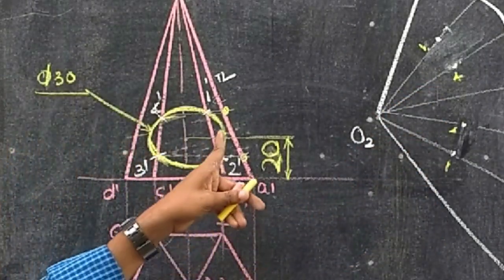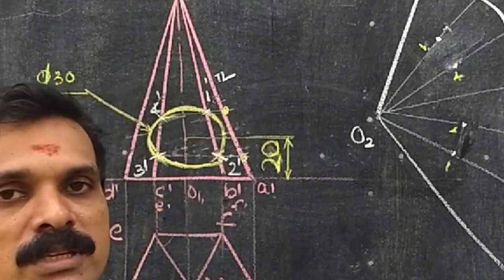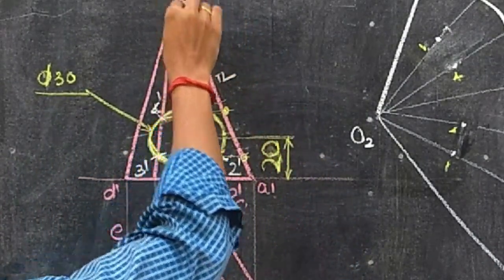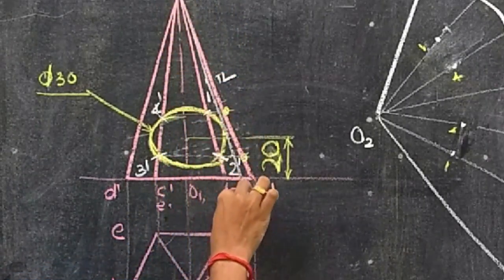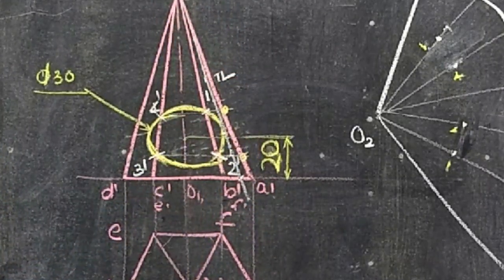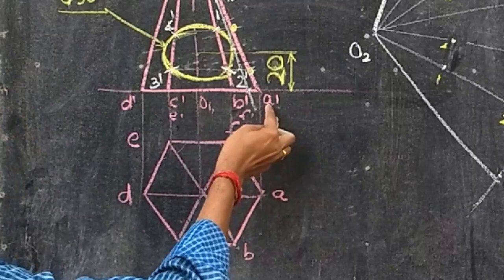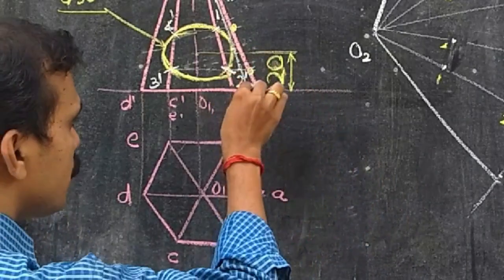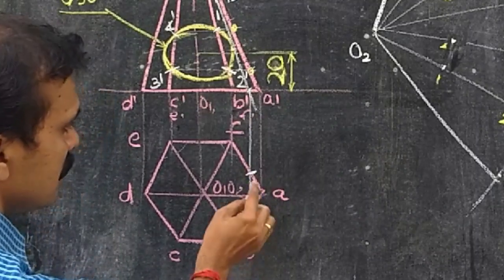And how can we construct this curve? How can we obtain the development for this curve? That is the important thing in this question. The method is, listen, draw a line from this point tangential to this curve, like this. You have drawn a line like this tangential to this curve. We have seen that that line intersects between A and B as well as between A and F at this point. So from that point draw a vertical line so that that line will intersect these 2 points.